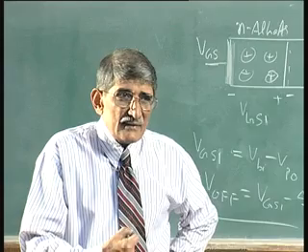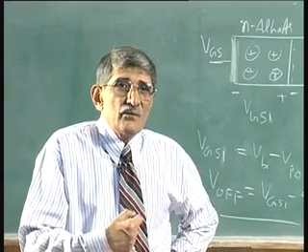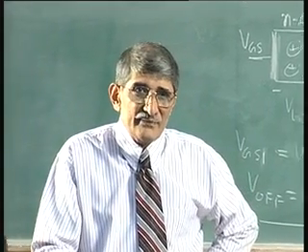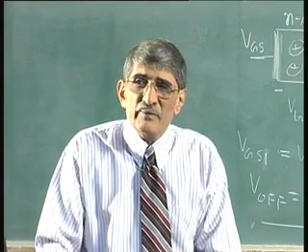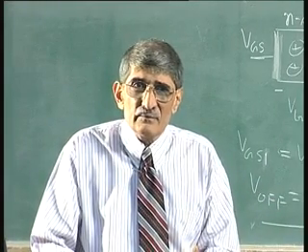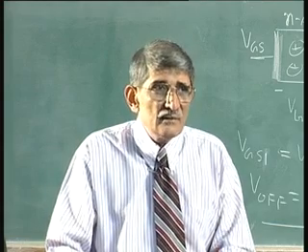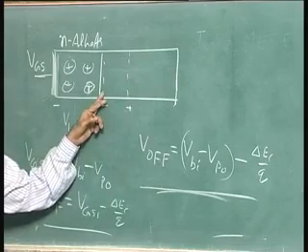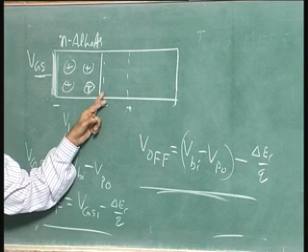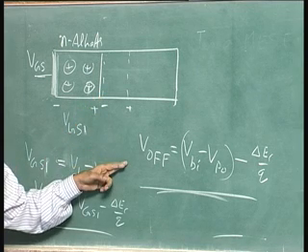Okay. You actually take that voltage as the voltage at which surface potential is twice phi f. It is equivalent of that. There are some electrons, but beyond that point, if you increase the voltage positively, you will have more electrons coming up. Okay. V off is very small, it is equivalent of threshold voltage.